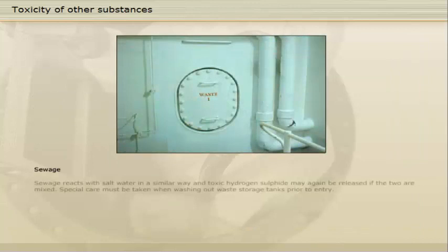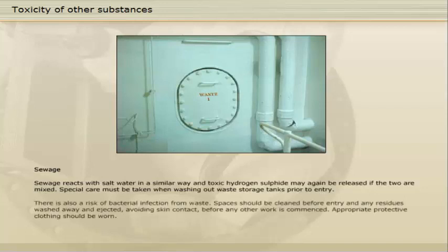Sewage reacts with salt water in a similar way, and toxic hydrogen sulfide may again be released if the two are mixed. Special care must be taken when washing out waste storage tanks prior to entry. There is also a risk of bacterial infection from waste. Spaces should be cleaned before entry, and any residues washed away and ejected, avoiding skin contact, before any other work is commenced. Appropriate protective clothing should be worn.